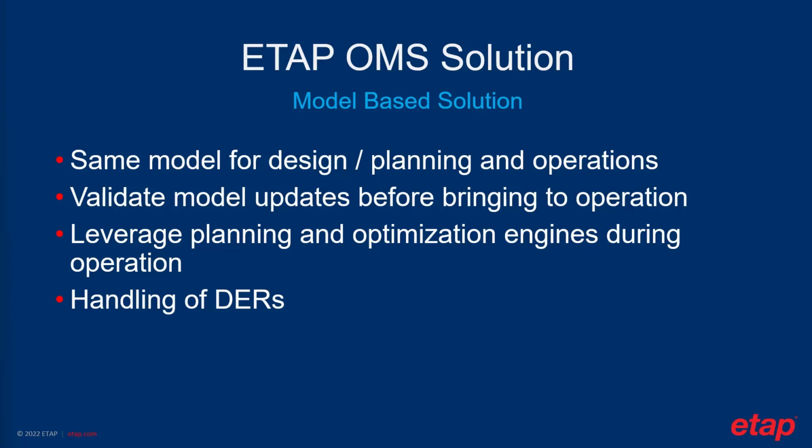Leverage planning and optimization engines during operations. We have all these calculation engines: unbalanced load flow, short circuits, switching optimizations, volt-var optimizations. All of those engines can be leveraged in operation time. So you can do predictive simulation, what-if analysis, and optimizations. All of that is just using the tools that we already have on the planning side, it's just being brought onto the real-time side.